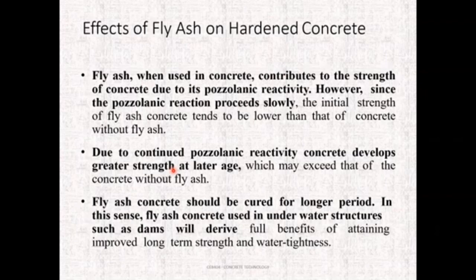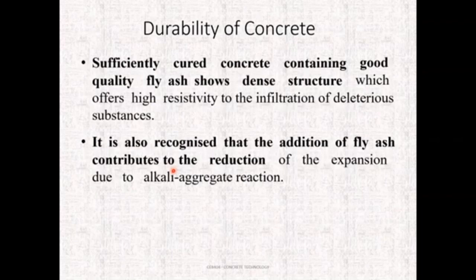In this case, fly ash concrete can be used in underwater structures such as dams, which will derive the full benefit of attaining improved long-term strength and water tightness. Durability of the concrete. Sufficiently cured concrete containing a good amount of fly ash shows a dense structure, which has a high resistance to the infiltration of deleterious materials. It is also recognized that addition of fly ash contributes to a reduction in the expansion of alkali aggregate reactions.